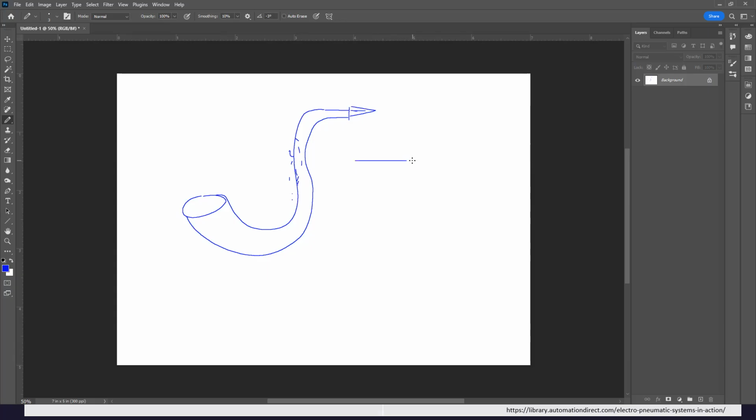If you magnify that, it will have two plates that, if you blow air through, start vibrating, and that's called a reed. So by the same token, a reed switch would be a couple of metal plates with connections, and if we put the magnet to it, those two touch. So that would be the reed switch.